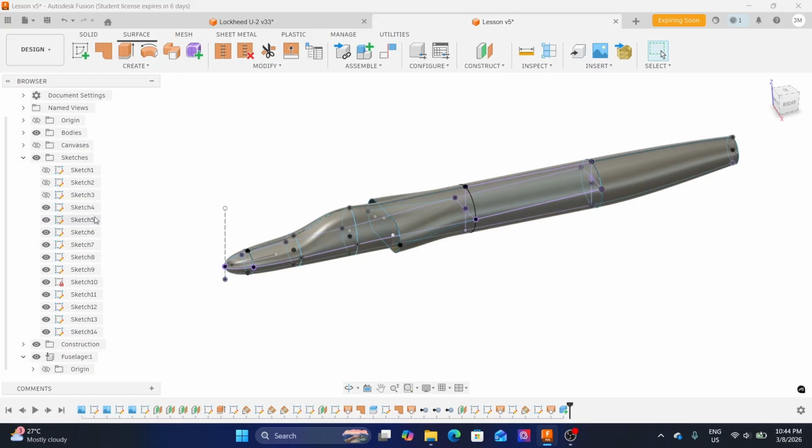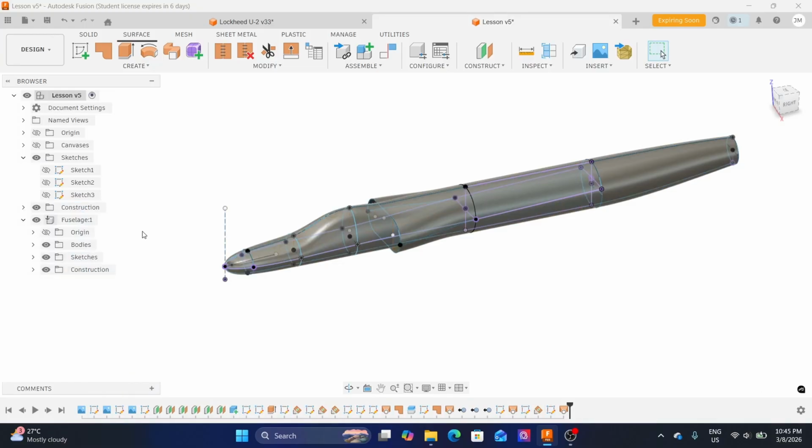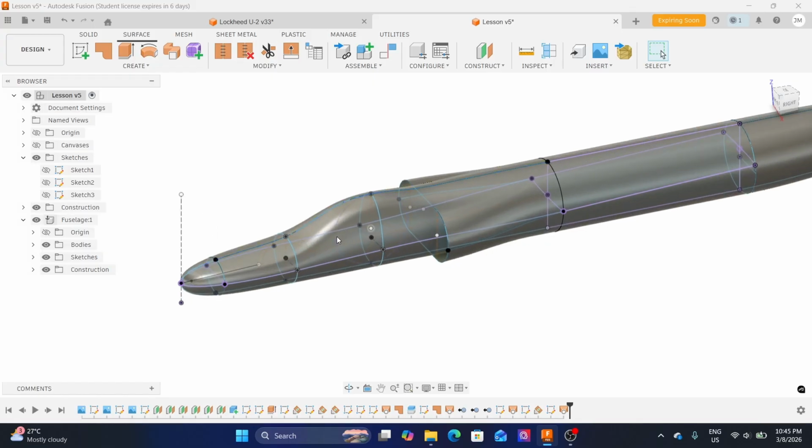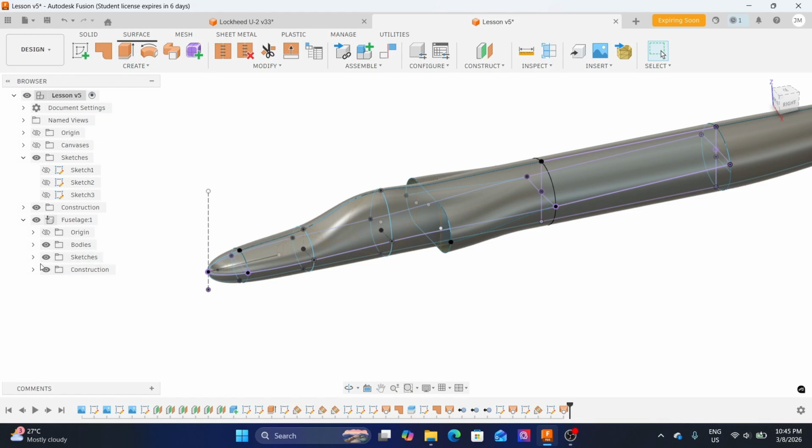The technique here is, if I select it from here and drag and move it under this fuselage, you would see that, since the 3D bodies and the construction planes are related to the sketches that we have made, it automatically detects that once we have moved the sketches where we created the bodies, it will also automatically move the bodies and the construction planes related to it under the fuselage section.